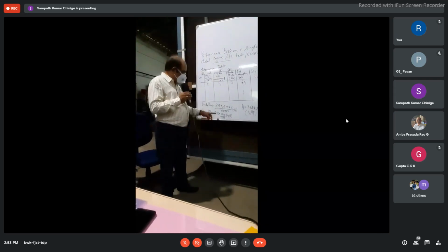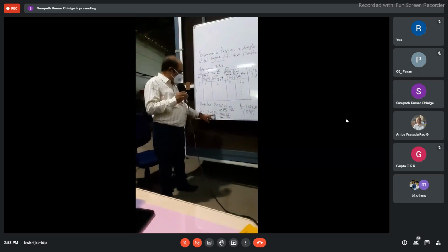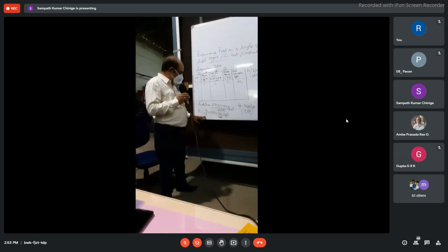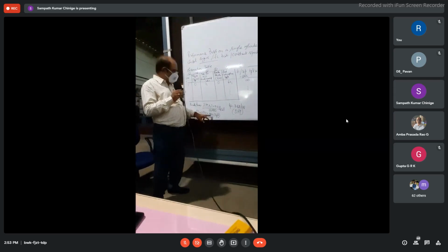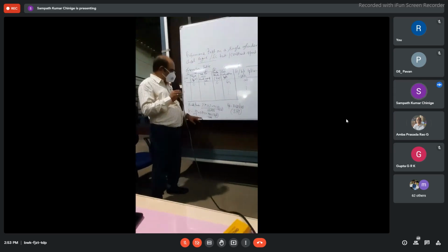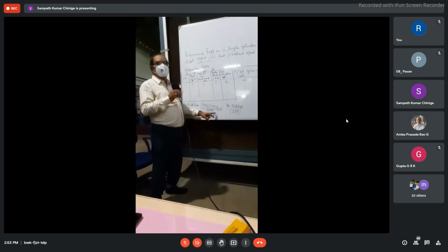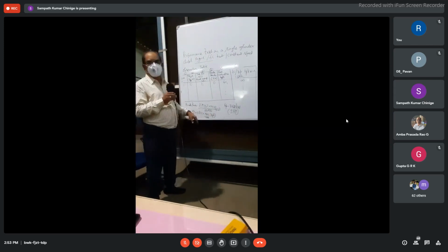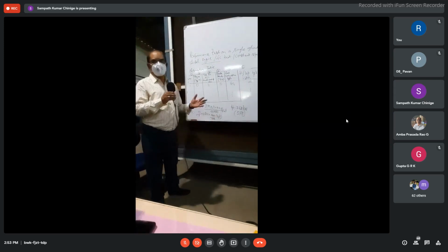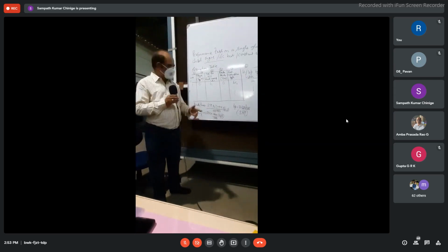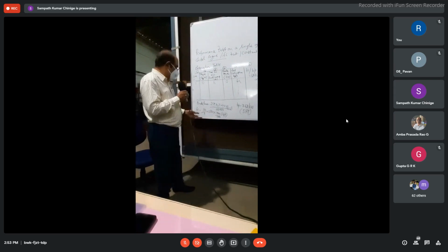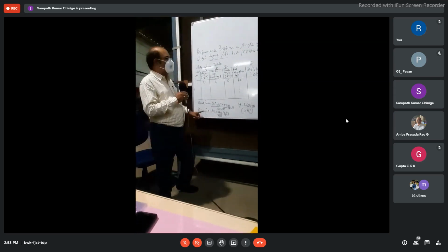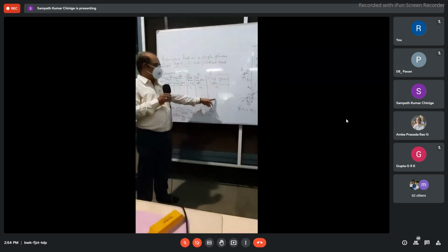So up to this, what you get is so many grams per second. These grams have to be converted into kgs by dividing by 1000 per ton. So now it is kg per second. To get it into kg per hour, you have to multiply by another conversion factor, from seconds to minutes and minutes to hour, so you get 3600. So in effect, you get the fuel consumption. Note down all the values and calculate all those values for fuel consumption.